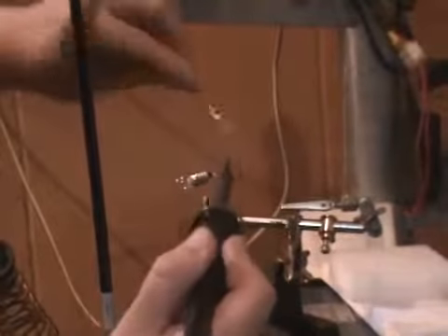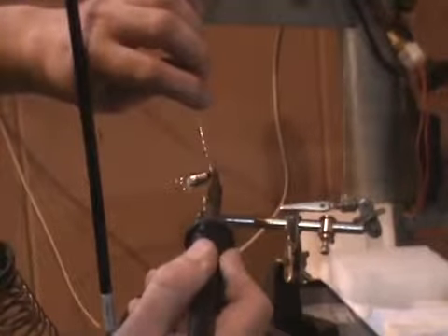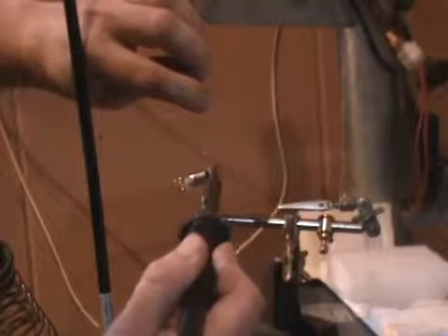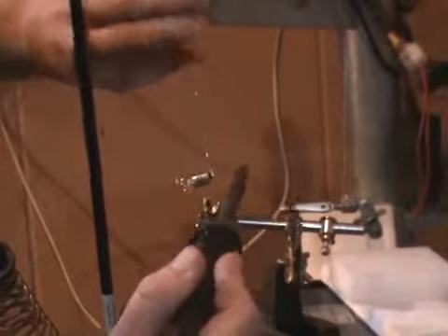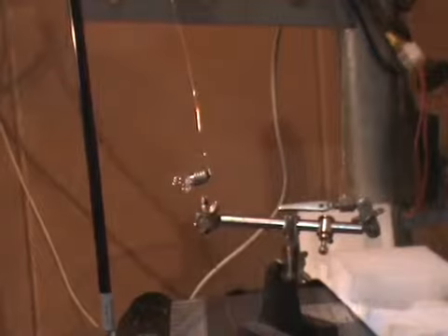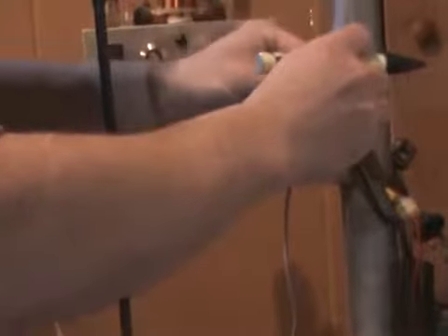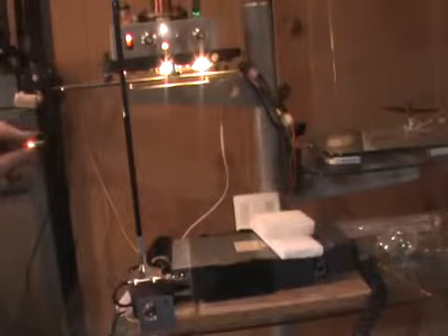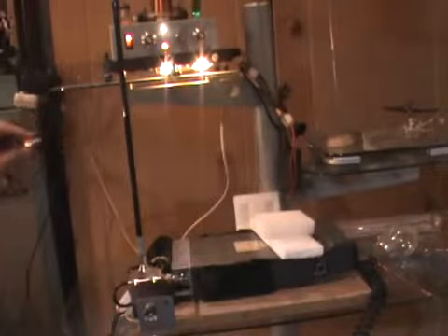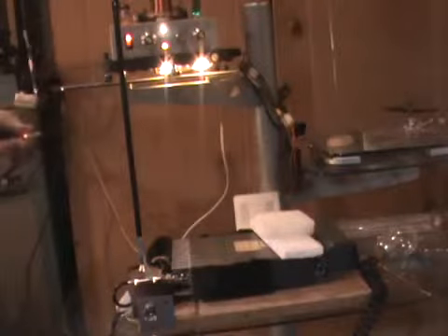To demonstrate this, I attached to a 6.3 volt 0.25 amp rated MES incandescent indicator light source 2 lengths of wire. The incandescent light source will illuminate, indicating when electrons flow. When we hold the light source and switch on the transmitter, we get a faint glow, but when we tune it precisely by shortening the wires slightly, in this case, the light source begins to illuminate to a higher degree as we tune it in.